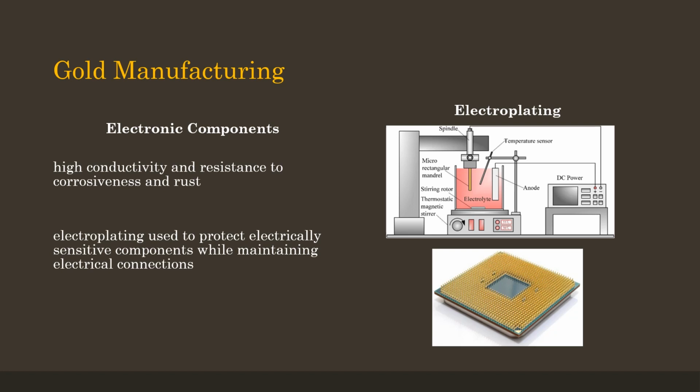The next process, a stainless steel rod, is used as the anode or the positive lead and is placed in a container holding the bath mixture with a plating voltage of around 4 to 8 volts depending on the size of the component. The mixture is heated to around 110 degrees Fahrenheit, and the electronic component is suspended in a cathode bar or the negative lead in this process.